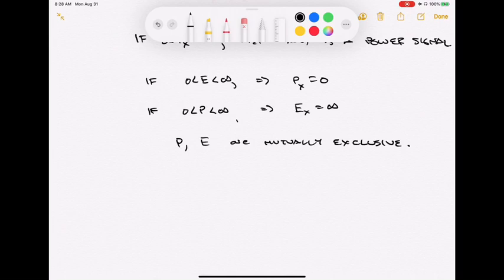So this is just our baby steps of trying to get into some sort of understanding or way of describing signals. We started out with a really basic one of energy and power signals. Why might we use something like this? Well, it turns out that if you have an energy signal, some types of math are more appropriate than if you had a power signal. When we later get to, for example, Fourier analysis, power signals require a different flavor of Fourier than do energy signals. So these signal classifications and descriptions just help us get a better understanding of a signal, and they'll point us to the right mathematics.